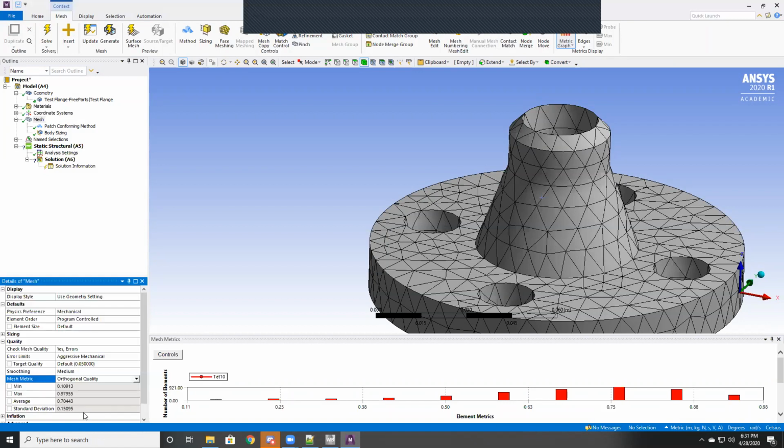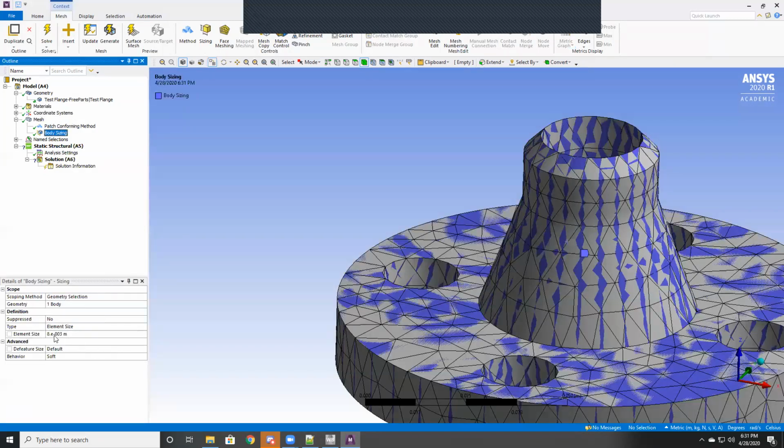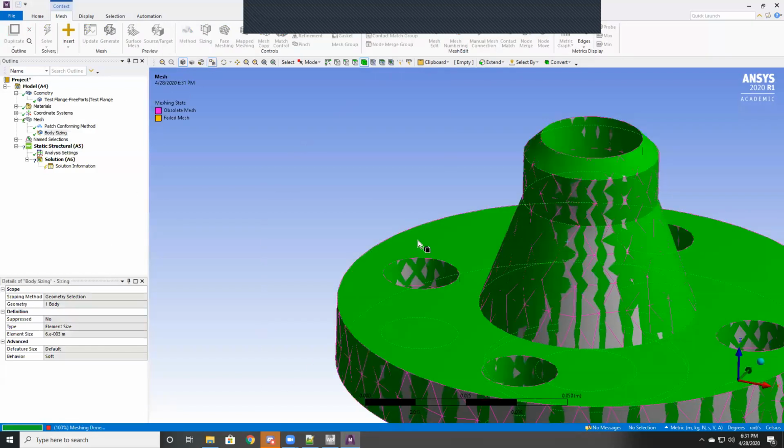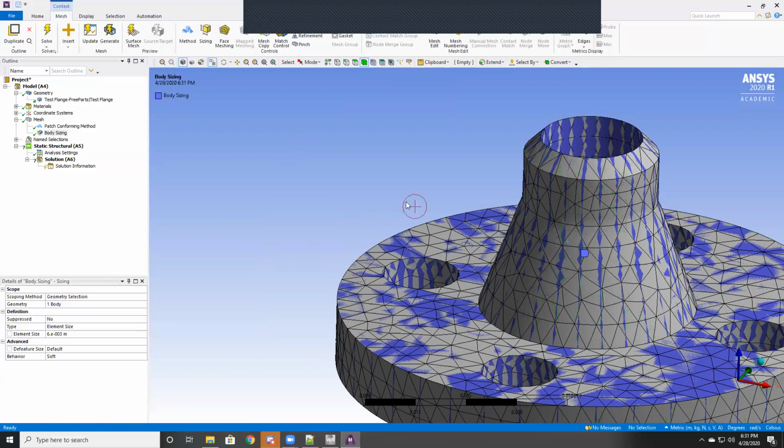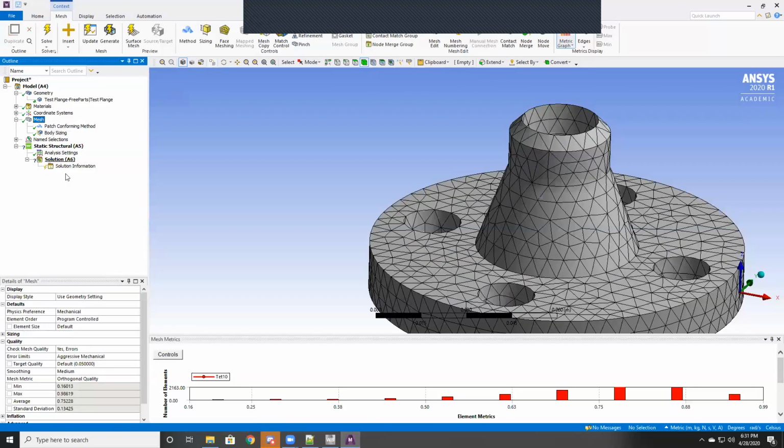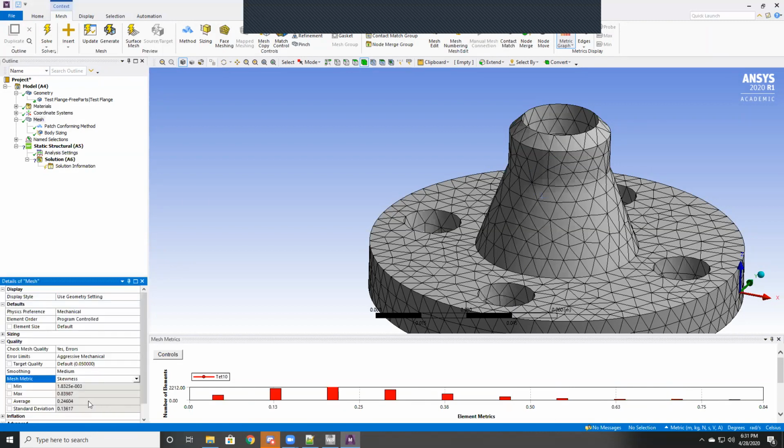However, the smaller the mesh, the more cells you have, and the longer it takes to simulate. I'm going to just make it a little bit smaller. We're going to set it to 0.006 and generate it, and you can see just the quality that we're going to get out of that. And it's not a huge improvement necessarily over the 0.008. You can see the orthogonal quality, the minimum's only gone up about 0.06, and the skewness has only gone down a little bit from just barely 0.89 to 0.84.